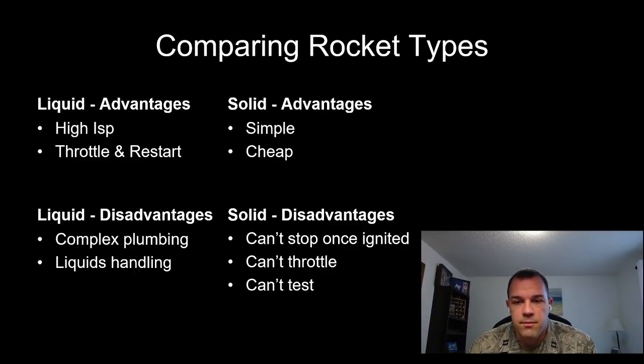The other major advantage of a solid type rocket is that you can store it for long term. So, for instance, the U.S. Air Force can throw those down to missile silo, and they can sit down there for years at a time without major maintenance. So, if we need to push the button and launch one of those puppies, they're ready to go. Liquids, on the other hand, you can't do that. If they're cryogenic, they're going to boil off pretty quickly, and the liquid propellants that aren't cryogenic are usually quite toxic and can end up eroding and oxidizing a lot of the plumbing that are used to capture it.